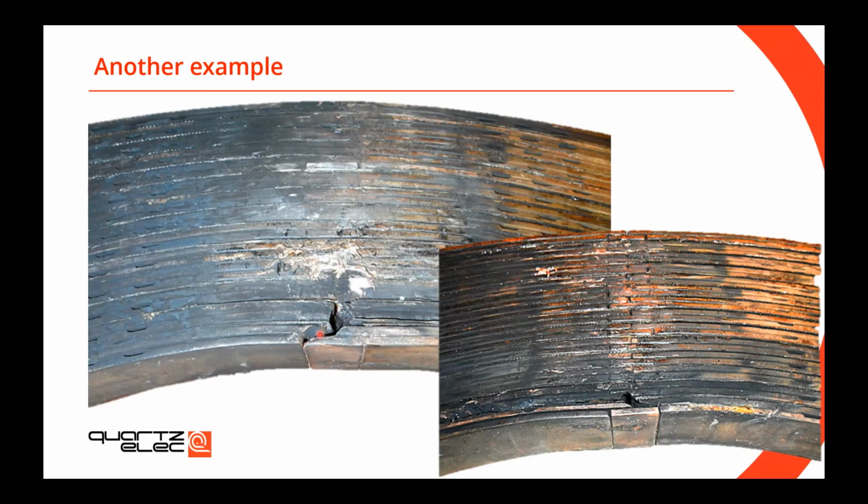And yet, you have significant damage going on here with the molten copper. You can see molten copper, disappearing copper. That means that the temperature here was more than 1000 degrees. I think 1100 is the melting temperature for the copper.